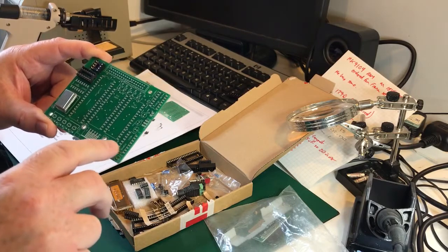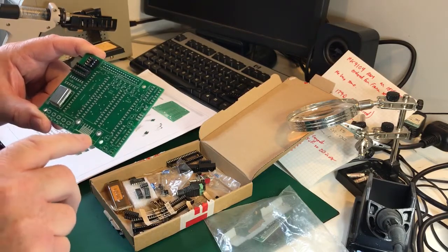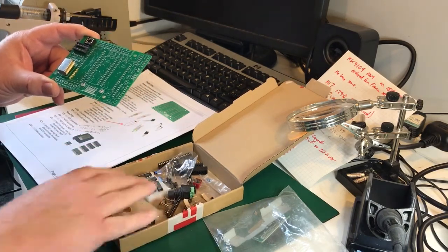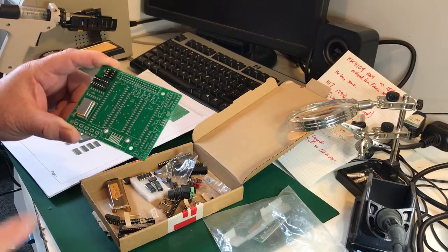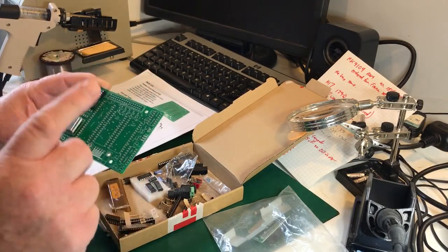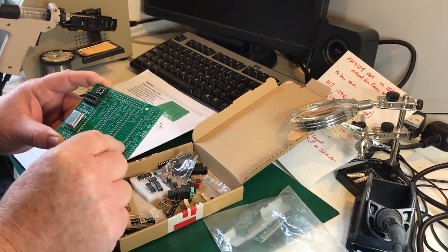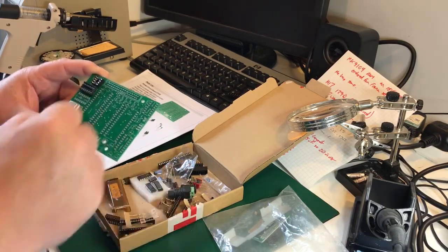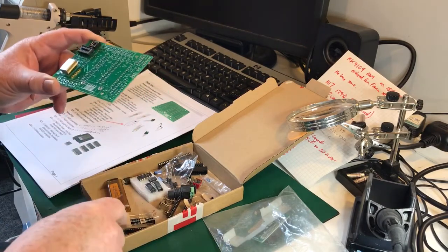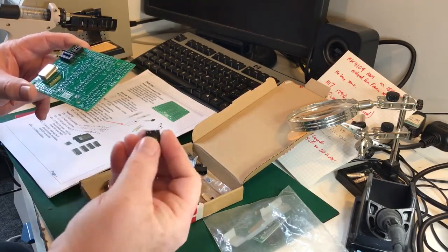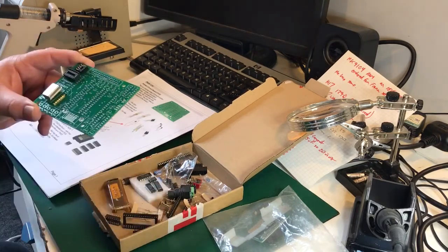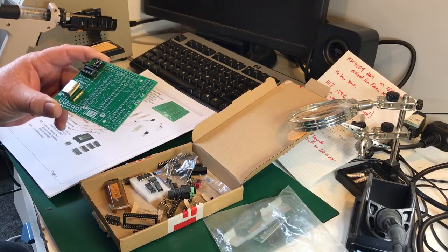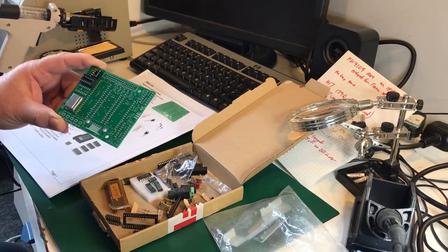I'm not going to fit the Max 232 and the RS-232 connector and the caps that relate to that. Although I've got them, I've put the kit together pretty much ready. I'm going to just solder the lead on and just tap off the TX and RX from the PIC directly, which means I can just use a standard 5V USB to TTL. I'll make another little adapter lead for this, which can just plug in on there, so that we can pick it off and use that for the moment for testing purposes. I will probably construct everything else.